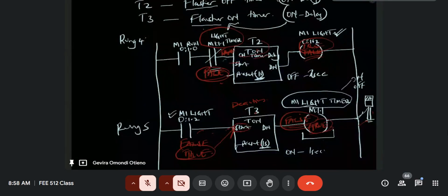And you can shut it down by providing a logic low or a logic false. Then you can shut it down. But as soon as you provide it with a logic high, it will delay the time it takes for the light to go on by 1 second, even if the previous state is false.